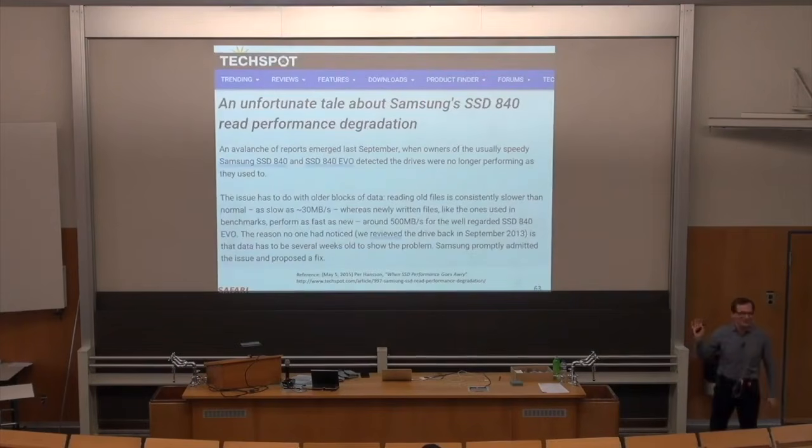So this kind of story happens actually in flash devices quite a bit. Basically, device performance degrades over time. By now, based on what you learned, this is not a surprise to you, right? Over time, you get more refresh, you try more of these error correction mechanisms, neighbor-assisted correction. As a result, your latency should increase over time, and your energy consumption should also increase.